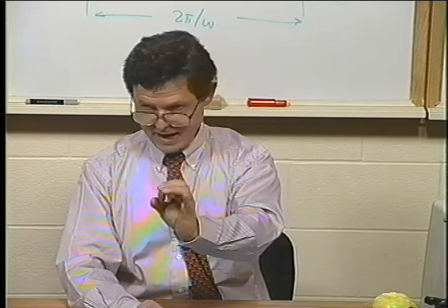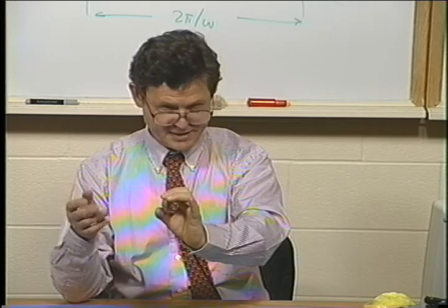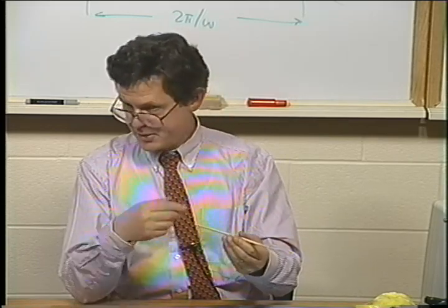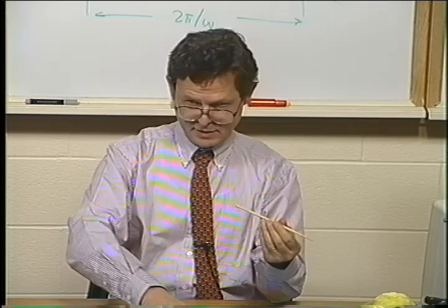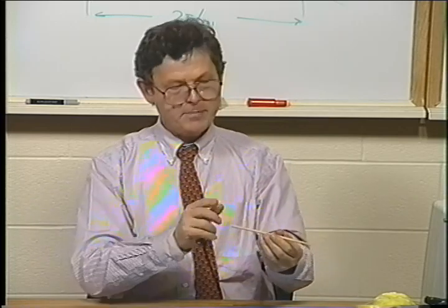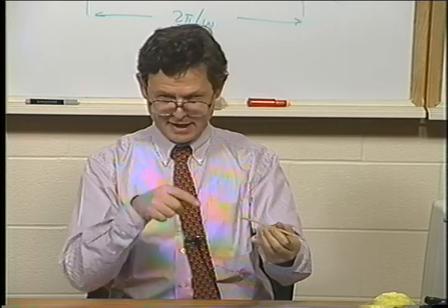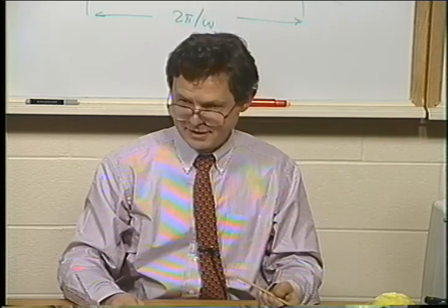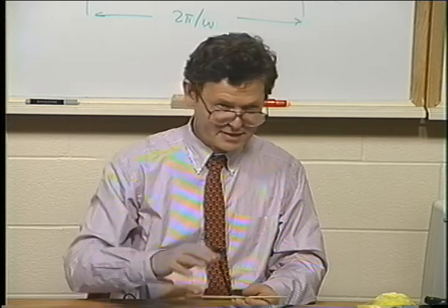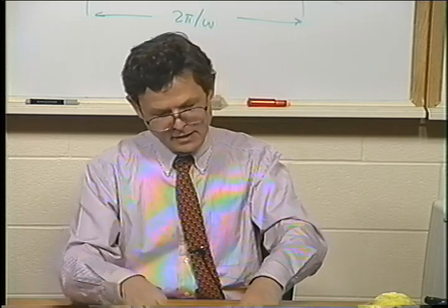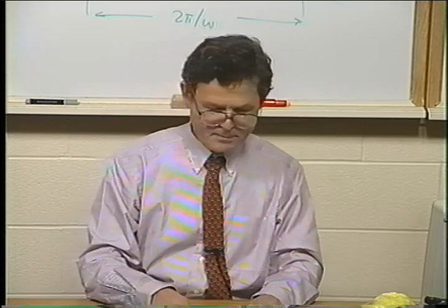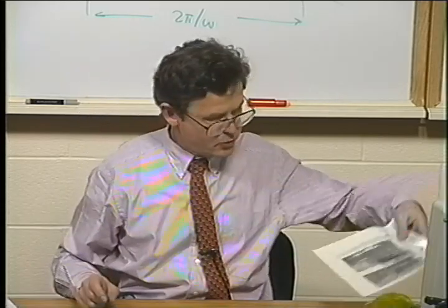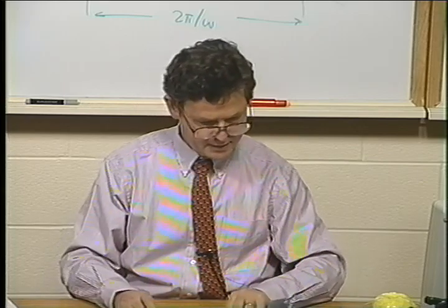When you extrude a strand, you produce some melt in an extruder, and you extrude it to make a rod, say. And you would want to increase your production. You go to higher and higher rates. And then you generate vortices like this, and they start to move around. And then when you extrudate, you will see that the history of the material elements is asymmetric, and you might have a corkscrew coming out of the die. So there's always a limitation in production because of instabilities, and one instability might come from this inlet region.